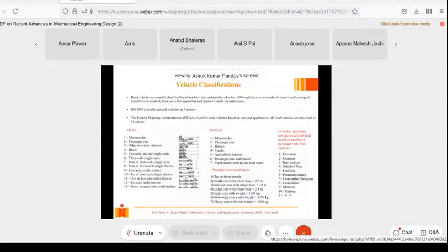Now, before we discuss other details, first of all, we have to see how we classify vehicles, right? Generally, vehicles are classified based on their size and number of axles. Here you will see that there are many standards. One is ISO 3833, which classifies ground vehicles in 7 groups. These are motorcycles, passenger cars, buses, trucks, agriculture tractors, passenger cars with trailer, truck trailer, and all that, right?